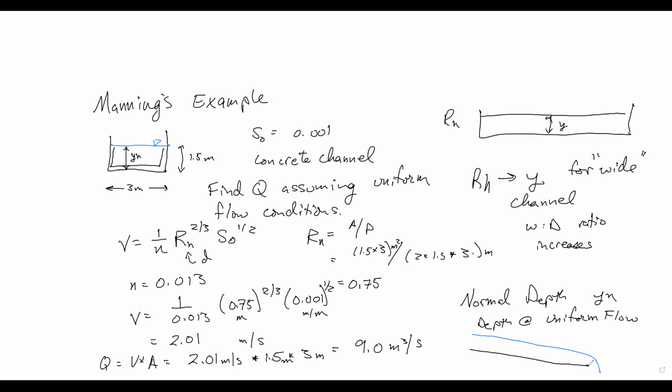Say we have a channel and there's a spillway or something like that and the water spills over. We're going to hit our critical flow depth at some point over that. We talked about that. We'll actually derive this next week. But we'll note that the depth is steadily increasing as you go upstream. As you go downstream, it's decreasing to go over that spillway. Under this condition, probably somewhere upstream we're going to achieve our normal depth, where everything's in balance, but there's some different boundary condition over here.